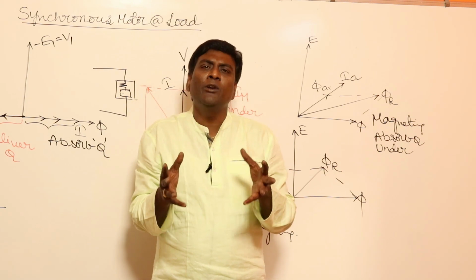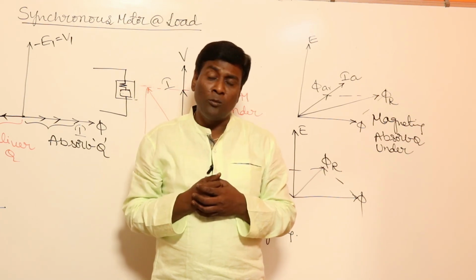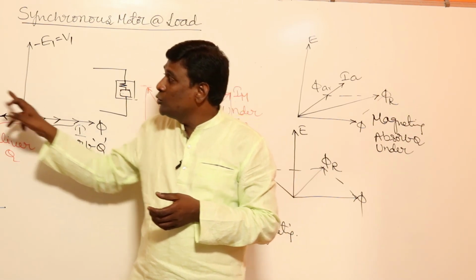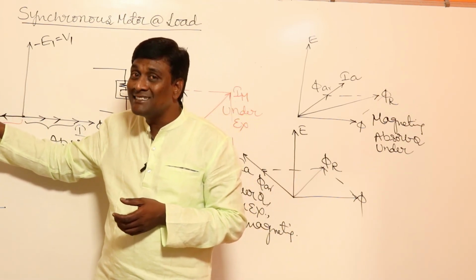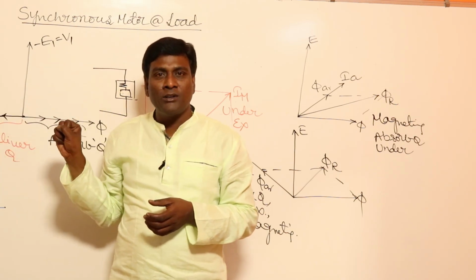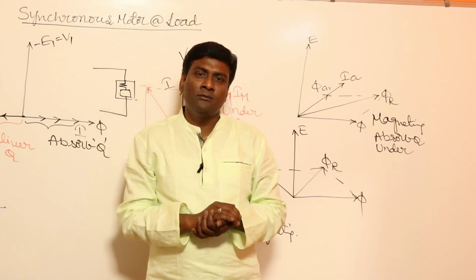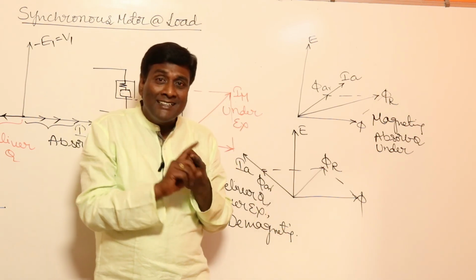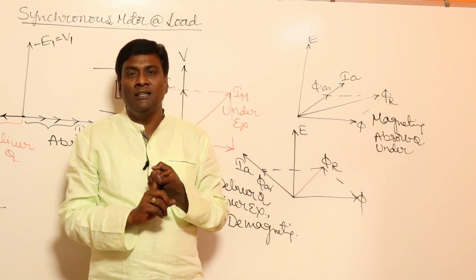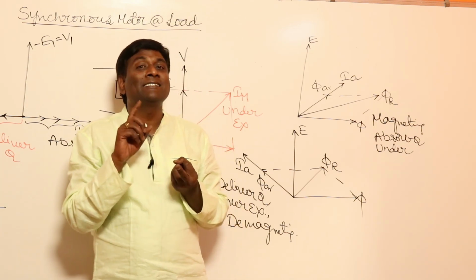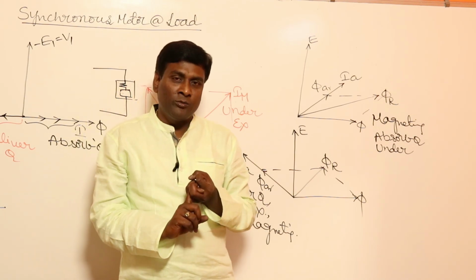So in a motor, when you get a lagging component of current, you are unable to set up the flux required by the air gap through the field winding. So it will take an extra component of current, so it will be absorbing reactive power. So the altogether conclusion is very simple. An overexcited synchronous machine delivers reactive power. An underexcited synchronous machine absorbs reactive power.